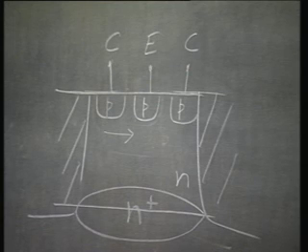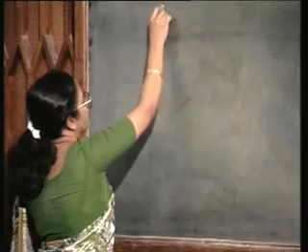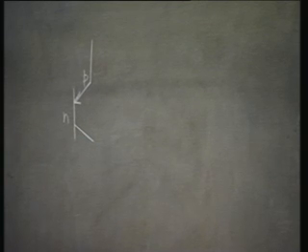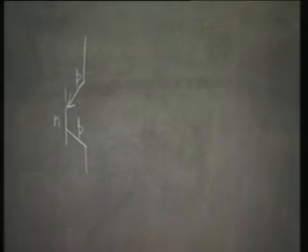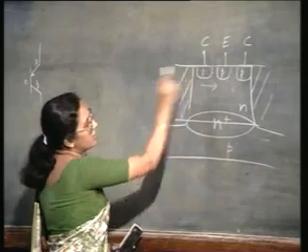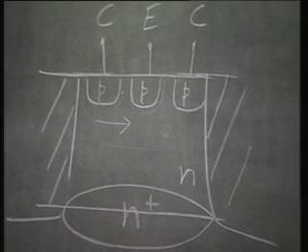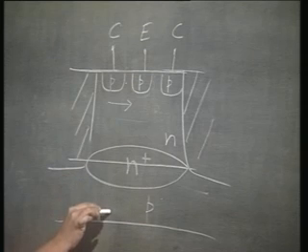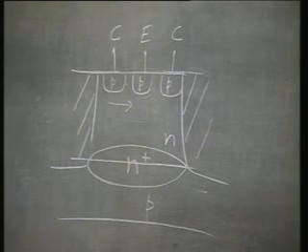Okay. Now, look at this transistor very carefully. What do I have? I have this collector P, then I have this base N, let us say this is the emitter P and this is the collector P. Base is N, emitter is P, collector is P. Now, look that there is another PNP transistor also available in the same diagram. What is that PNP transistor? One is collector, base, substrate, emitter, base, substrate. In both cases the bases are common. So, I have this base,